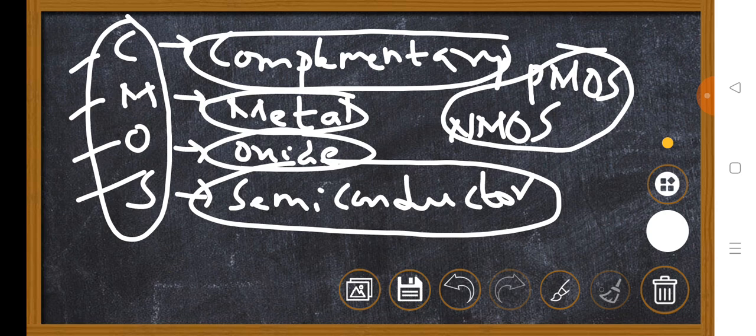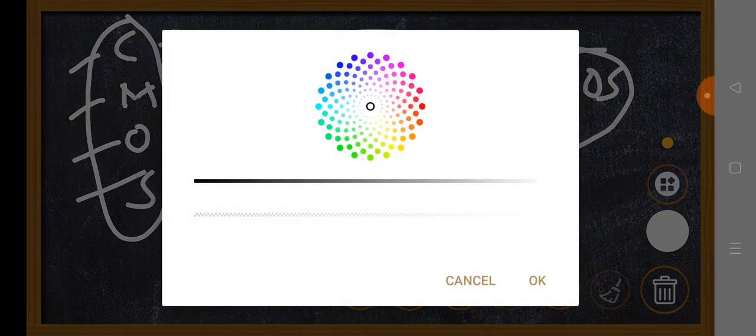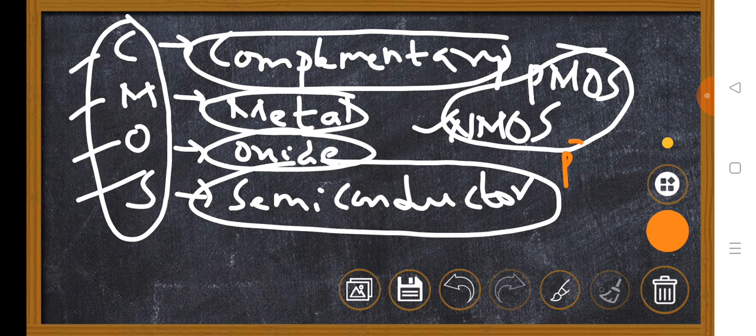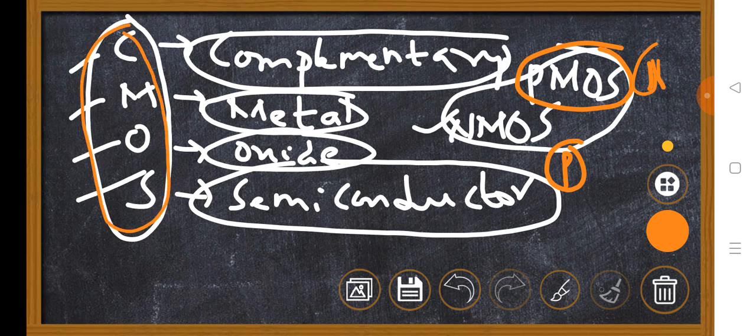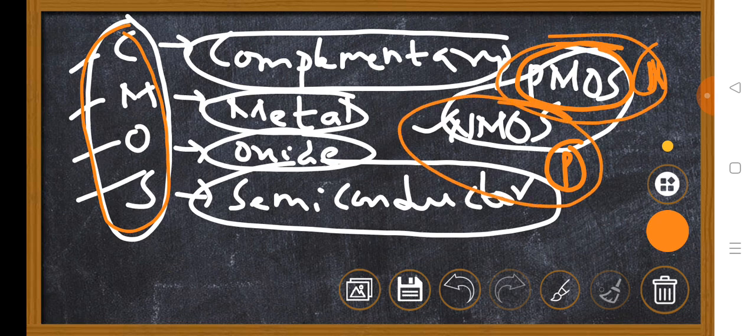We know very well, to fabricate an NMOS transistor, which substrate do we require? We require a P-type substrate. But to fabricate a PMOS transistor, which substrate do we require? Absolutely, we require an N-type substrate. Is it clear? But here we have to fabricate CMOS. That means in a single IC we require NMOS and we require PMOS. Then does anybody have any idea how to fabricate these two transistors in a single IC? Yeah, absolutely. We have to take two substrates. That means one on another. Let us consider it is one substrate, you have to form another substrate.